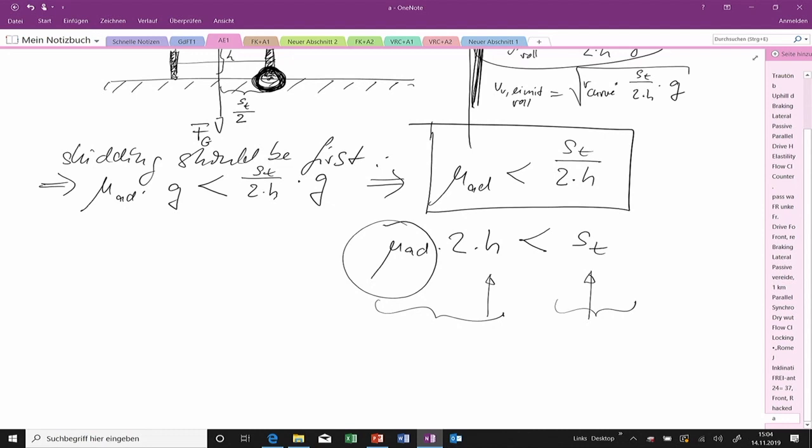And then the spring is compressed. Now the spring creates a force backwards, downwards. This will stop the mass somewhere. And then the mass will be accelerated in the opposite direction. Now it gets a speed, has some kinetic energy, is crossing the center, but because of the kinetic energy, it just continues. And then the spring will be elongated and creates a force upwards. So we have a system which is able to oscillate, and this goes on and on, and if there is no damping, it will never end. So that's an oscillation.